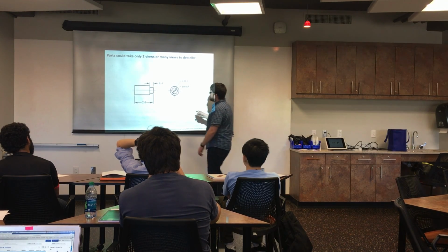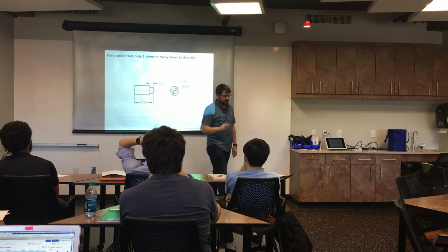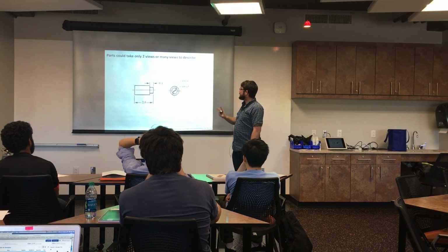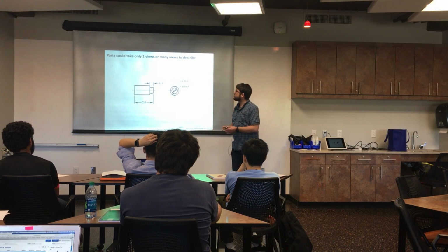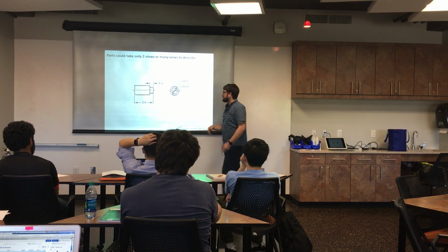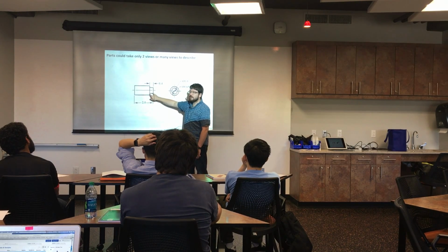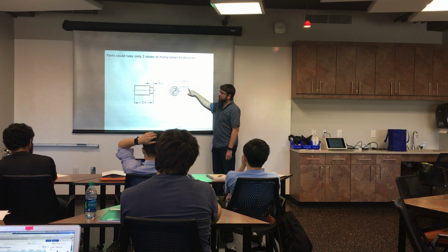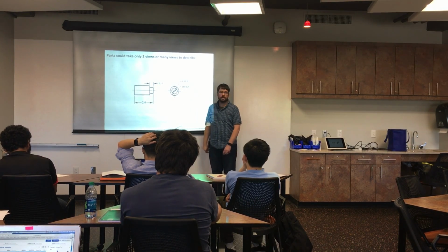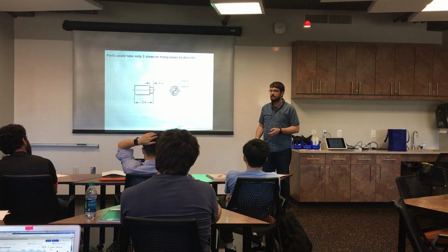And so this part is a little shaft that's got a turn down bit here. So it's only going to take 2 views to completely describe that part. You don't always have to use 3. This is especially true on cylindrical parts. So we've got a side view where you can see how long it is, how long this turn down part is, and then an end-on view where we see the diameter of the turn down is 650 thou, and on the outside it's 1 inch, or millimeters if this were a metric drawing. Does that make sense to everybody?